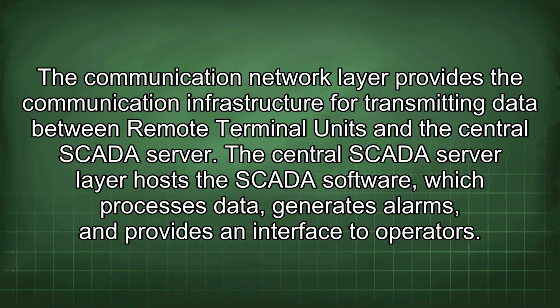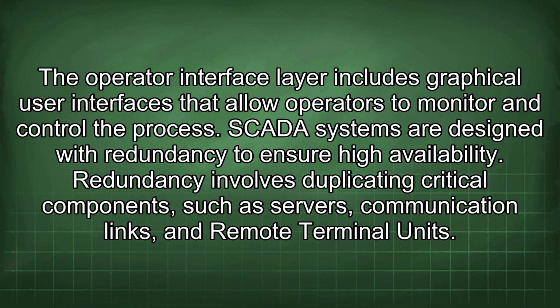central SCADA server. The central SCADA server layer hosts the SCADA software, which processes data, generates alarms, and provides an interface to operators. The operator interface layer includes graphical user interfaces that allow operators to monitor and control the process.